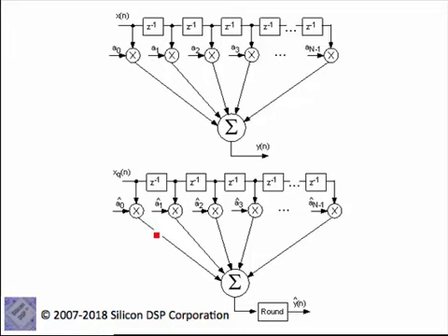So the fact that you multiply in fixed point does not introduce any error. All these multiplications produce, for example, in the case we were dealing with 16-bit word lengths here, 32-bit results. The accumulator, which is a fixed point accumulator, accumulates all the results, and we're assuming that the size of the accumulator is such that we don't have overflow. All the accumulation is done in 2's complement so that you can have intermediate overflow conditions. As long as the final result is bounded, you don't produce an error, you have an accurate result.